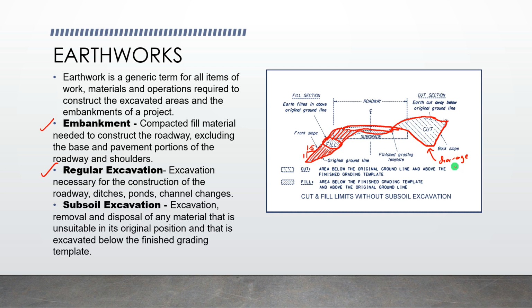So depending on the requirement, if drainage is required on the cross section of the roadway that is being designed, we put drainage such as line canal or earth canal. In this example, this is an example of earth canal, where we just excavate some portion